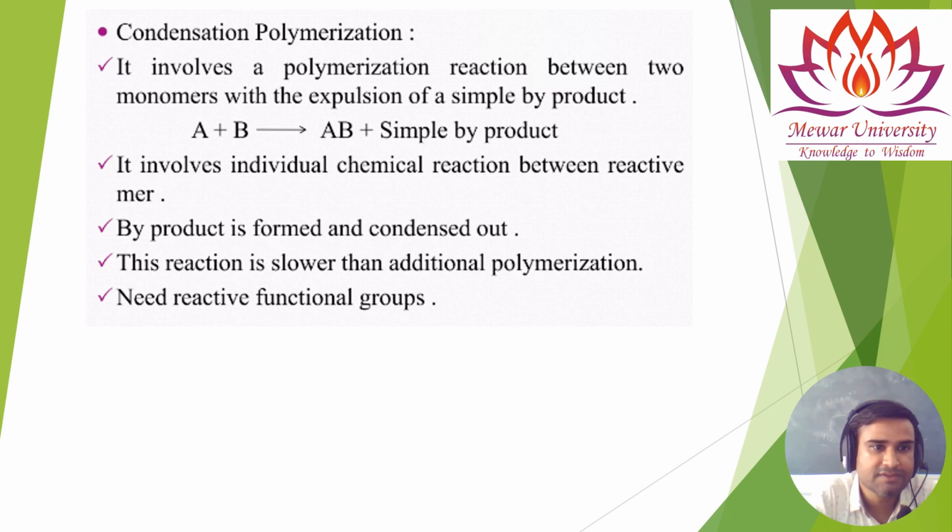It involves individual chemical reactions between reactive mers. The byproduct is formed and condensed out. So this reaction is slower than addition polymerization and it needs reactive functional groups.